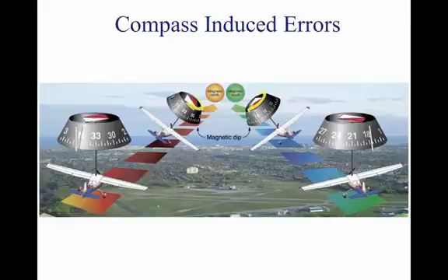When an aircraft flying on a heading of north makes a turn toward the east, the aircraft banks to the right and the compass card tilts to the right. The vertical component of the Earth's magnetic field pulls the north-seeking end of the magnet to the right, and the float rotates, causing the card to rotate toward west, the direction opposite the direction the turn is being made.